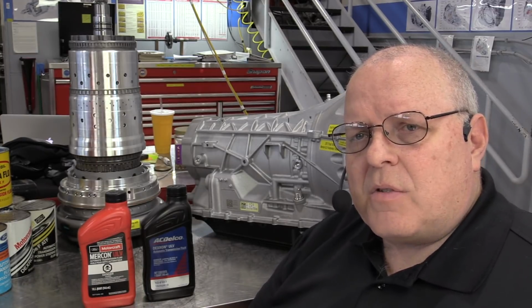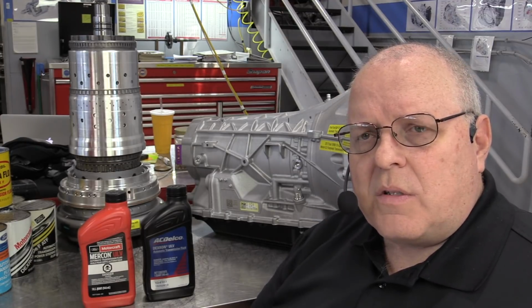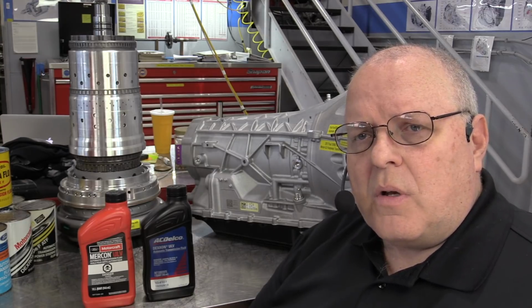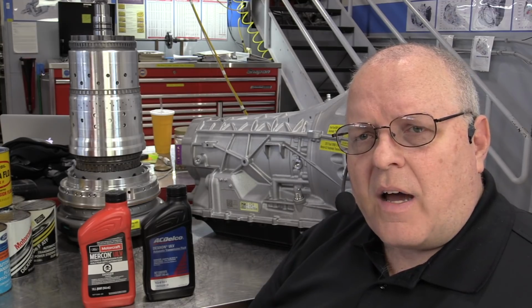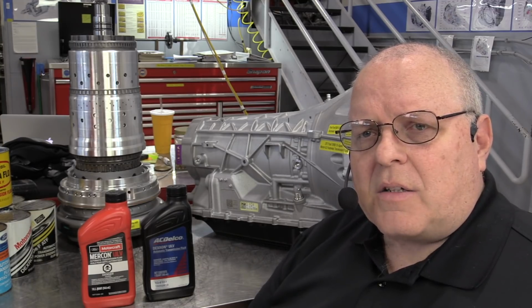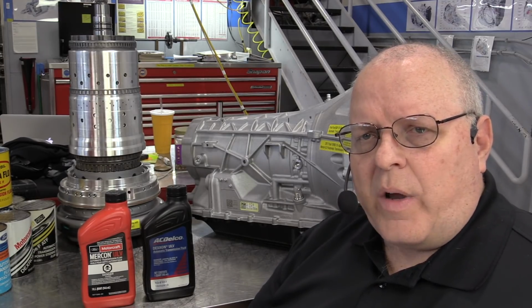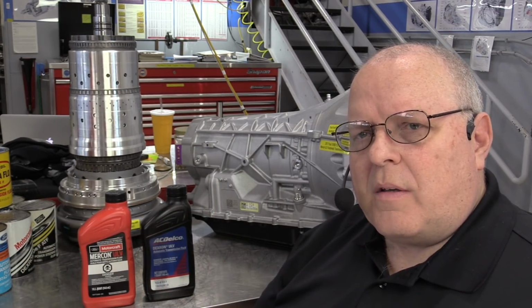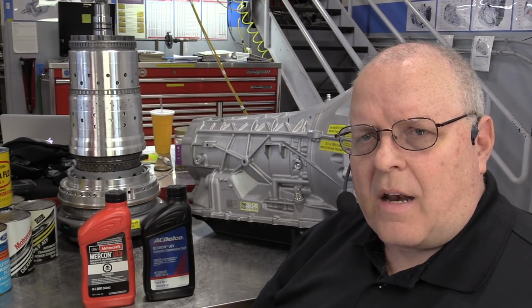It's the additives and the electronic controls, the programming of the solenoids in the transmission or transaxle to make that transmission work as it should. The compatibility with the seals and the plastics and the nylons and the clutch packs and bands on the older transmissions, the anti-foaming, the anti-corrosion, the anti-shuttering, and all the other issues that can be unique to a specific transmission are addressed with those additives.